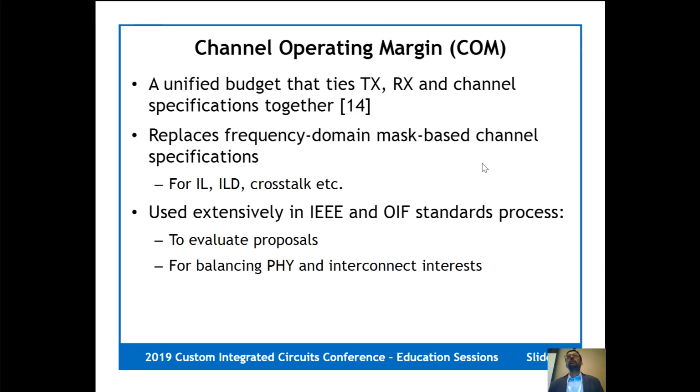It's basically a way to tie your SerDes and channel specs into one, rather than specifying them piecemeal. So it used to be that the standards would say, okay, the transmitter needs to meet this mask, the channel needs to meet this mask, the receiver should work with this input mask. But that quickly became unworkable at these higher signaling rates and with PAM4 modulation, given the significant interactions between all these components. So COM was proposed and adopted as a way to tie all these together.